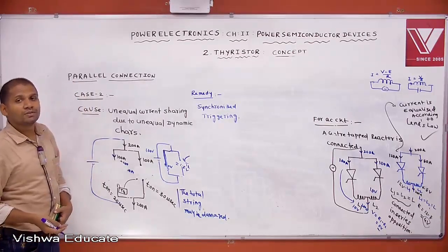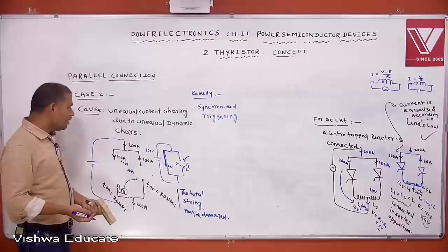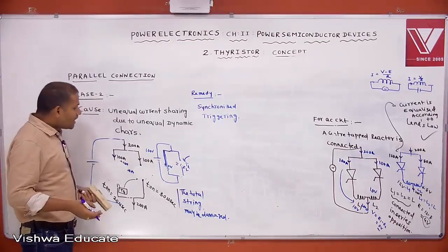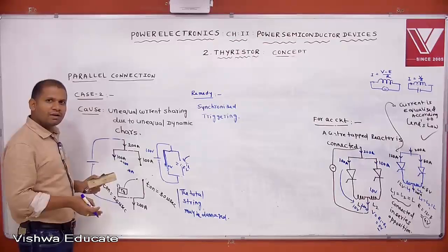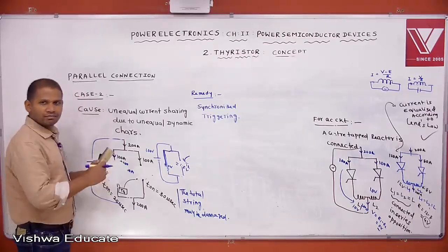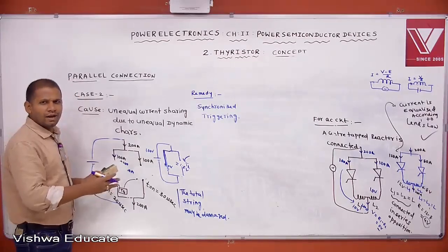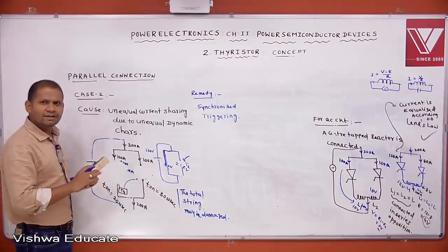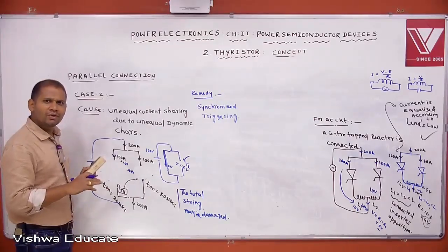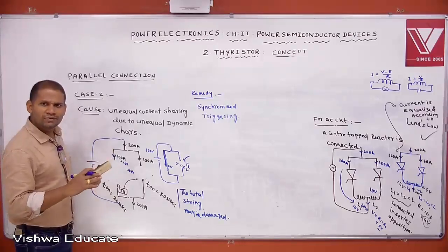Sir, how is it possible? Yes. Don't think that because both the SCRs are of the same rating they have the same turn on time, so just give the triggering pulse at a time. Don't think like that. The turn on time is mentioned in the data sheet. According to the data sheet, we can design the trigger circuit in such a way that both the SCRs will turn on at a time.